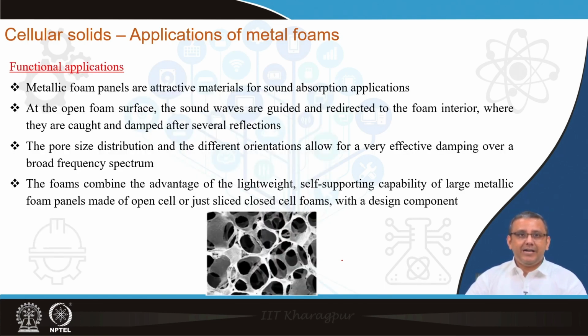These were about the structural applications. Metal foams also find several functional applications. They find applications as sound absorbers, as thermal materials, as filters and so on. In this particular slide I show you an open cell foam, and these kinds of open cell foams are extremely important for sound absorption applications. As you know by now, there is a fundamental difference between an open cell foam and a closed cell foam.